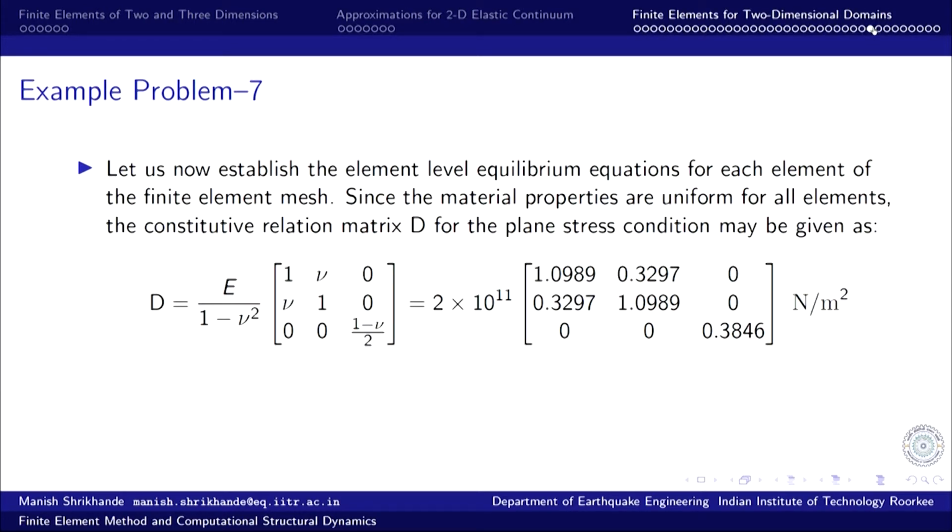Once we reassure ourselves that the problem being dealt with is consistent with the assumptions of plane stress conditions, then the constitutive matrix for plane stress, which is given by this, can be derived in terms of the element properties, that is Young's modulus and Poisson's ratio. This is the constitutive matrix for plane stress conditions.